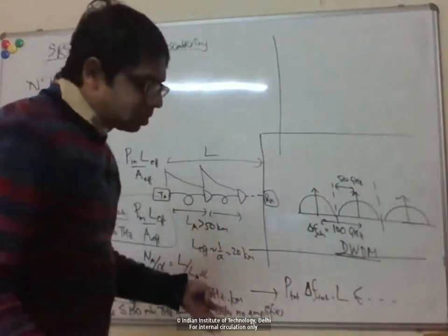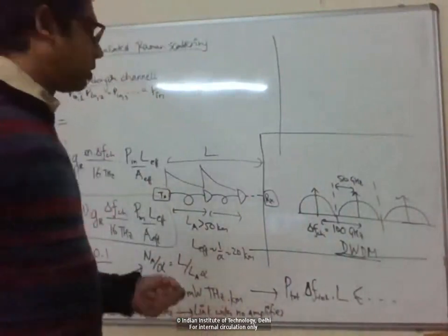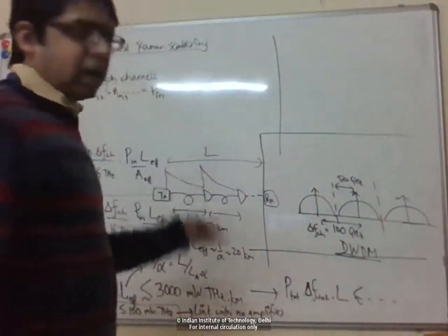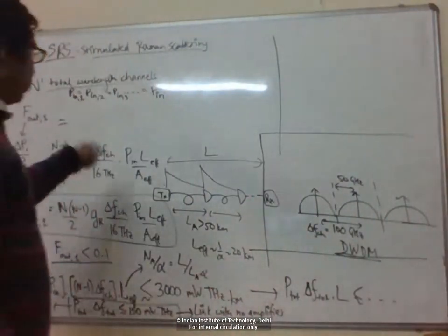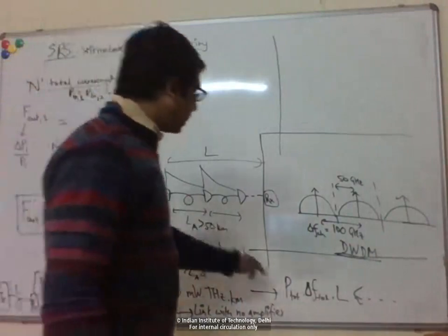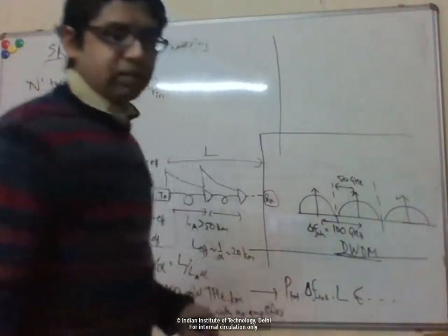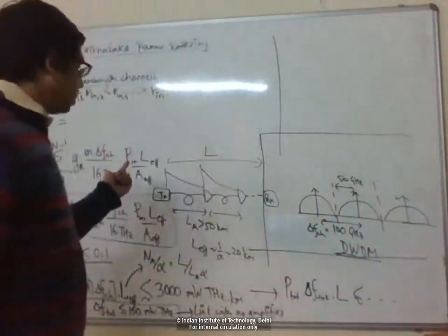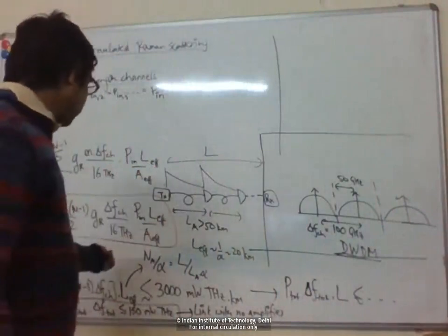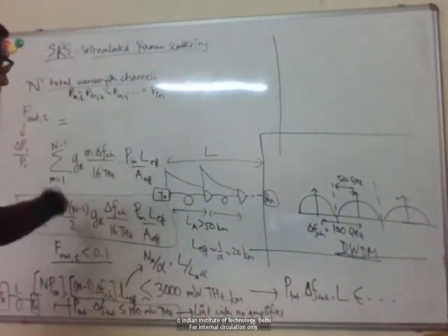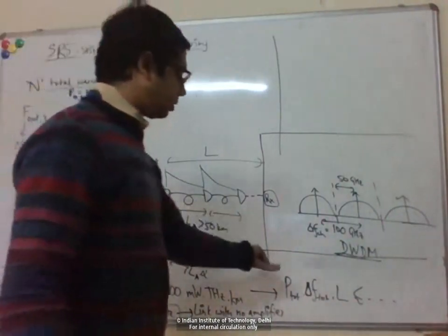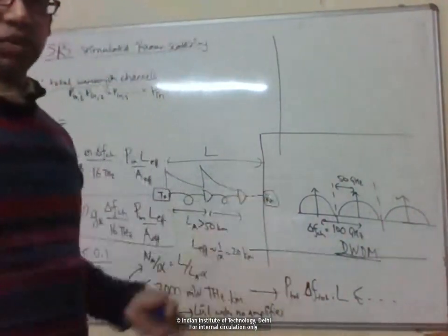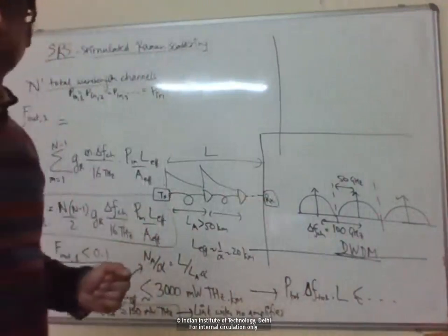So the system performance improves. If we just include linear effects, then the more power we have, the better the system performance. But now when we include nonlinear effects, we can see that there is a restriction on the power. If I keep increasing transmitter power, beyond some point the nonlinear effects distort my signal so that I actually start losing instead of gaining. That's what this is saying.